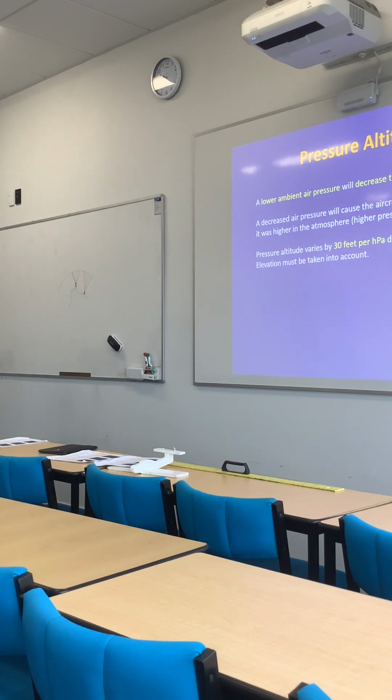When we're calculating our pressure altitude, we also have to factor in the elevation of the runway, not just the pressure of the day, but also the elevation that we are taking off from. And there's a really easy way to calculate our pressure altitude. Here it is here.